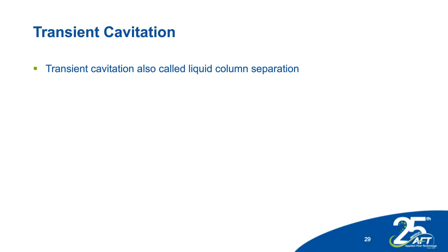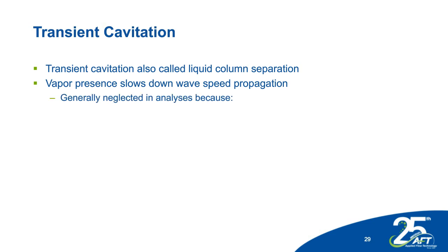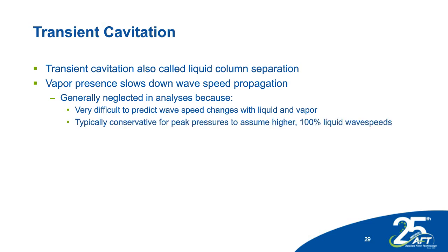But just long story short, transient cavitation is when your system pressure drops below your vapor pressure and a vapor volume can form. Like I said, it's similar to popping balloons inside of your pipes, and that can cause very high pressures and cause a lot of damage.